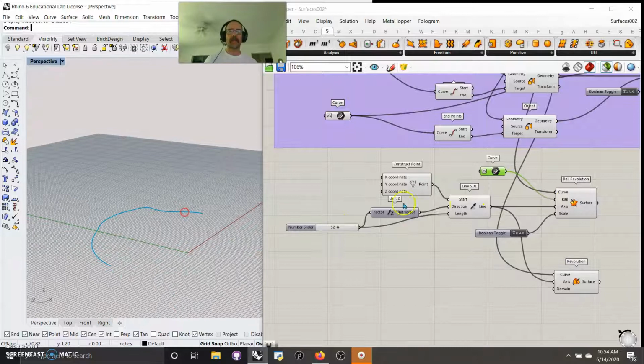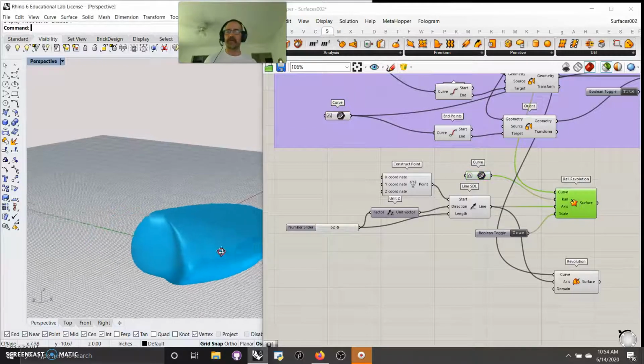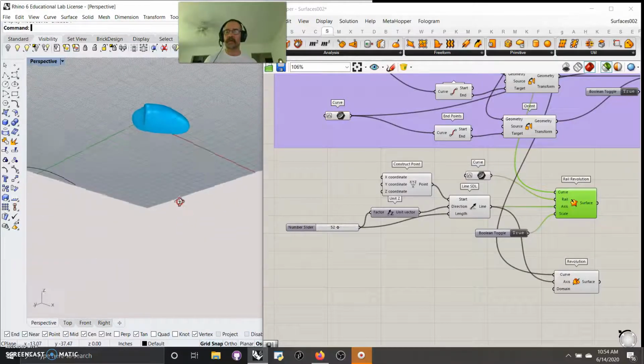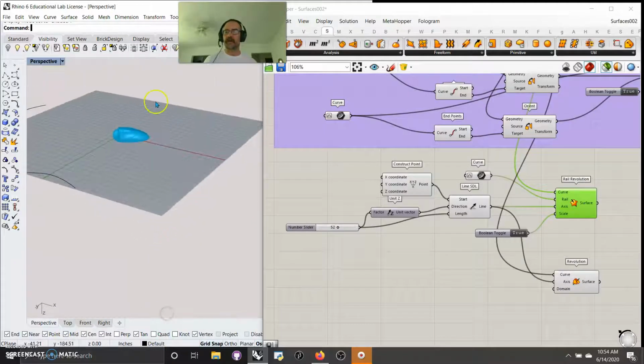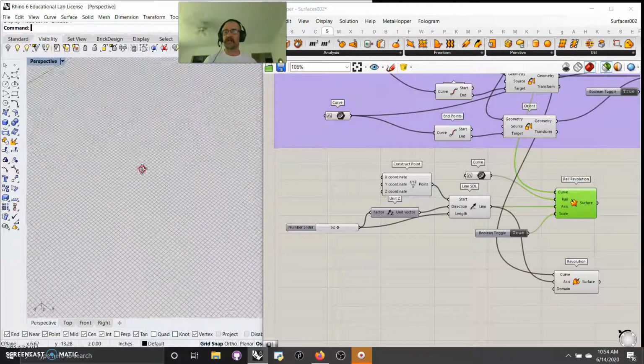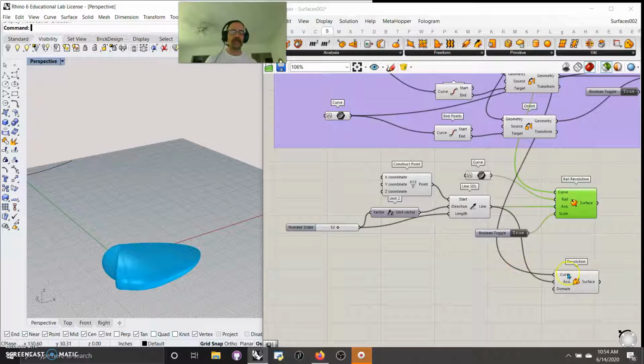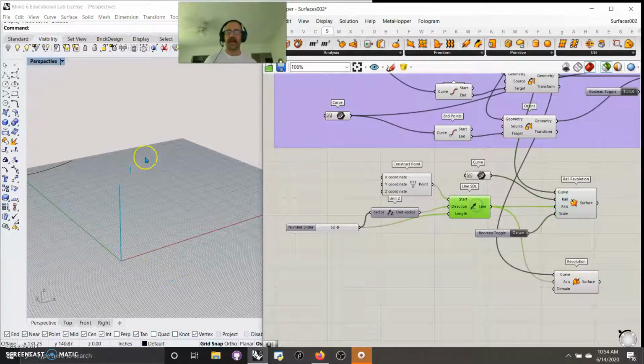Take my rail and use a rail revolve. I took a curve beforehand, and I'm going to revolve it along that type of curve. And I end up once again with a pretty cool piece of geometry that you can think about how that actually worked as a rail form. You can come up with some pretty cool things. Otherwise, you've got a rail revolve, and I just chose a simple axis straight up, and I took a circle, and in choosing that circle, or that point, and doing a revolve, I think my curve was basically a circle.